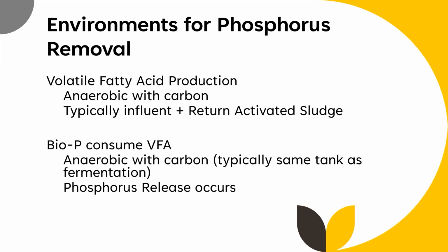So it doesn't make a lot of logical sense, but if biological phosphorus removal is working at your facility, the water out of your fermentation area, your anaerobic zone where VFA is being consumed, should be about 3 times higher in phosphorus than what is coming in.